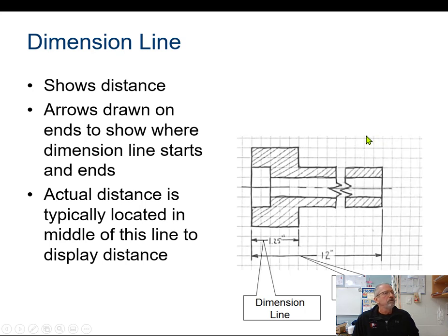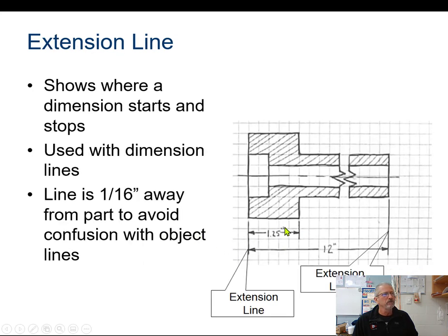So dimension lines show the actual dimension. We've talked about that. We've placed those on some of our work now. And so dimension lines have the actual distance of what the object is. We don't include inch marks. We are Americans. We think that everybody uses inches, so we assume that these are going to be inches unless it's otherwise stated. Okay, extension lines extend out, they never touch.